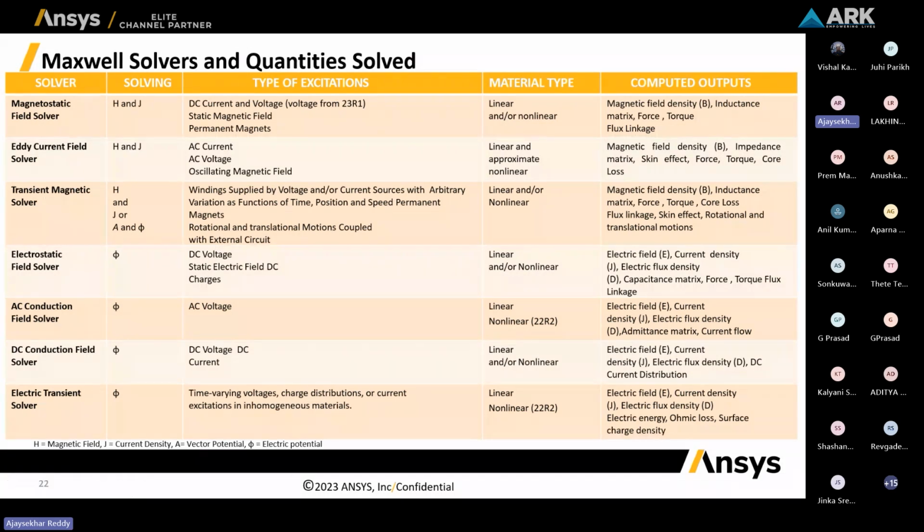Whereas the magnetostatic and transient analysis solvers will directly calculate the loss. Instead of calculating the resistance of the winding, they will directly give you the solid loss if you have a solid conductor, or the stranded loss if you have a stranded conductor.